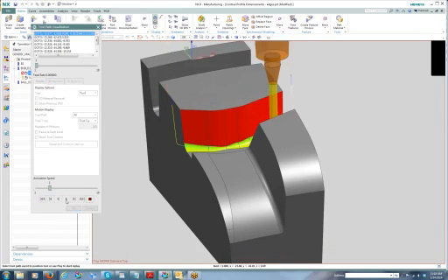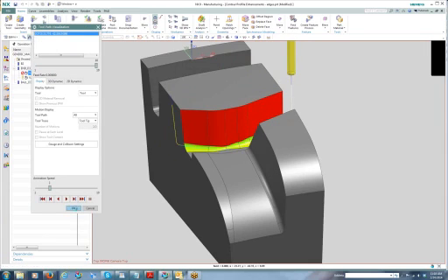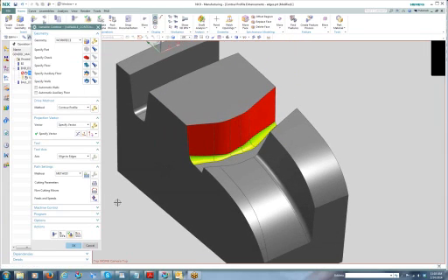Even though they're not necessarily straight or easy to be machined? Because I can see that there's some inconsistencies just in the wall there. Right. So sometimes in other CAM systems, the tool is going to want to follow the UV direction of the surface. That's an internal designation of the surface. We can do that, but in NX we can also tell it explicitly to follow whatever edges are modeled on the part.